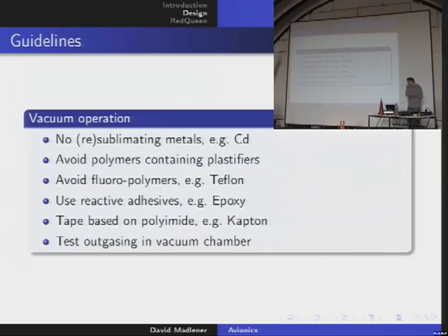And again, testing. Build a vacuum chamber and check if your electronics will outgas in vacuum, and if your electronics will survive, and if the thermal management will work. So if it will heat up, or cool down too much, that can be tested in a vacuum chamber.